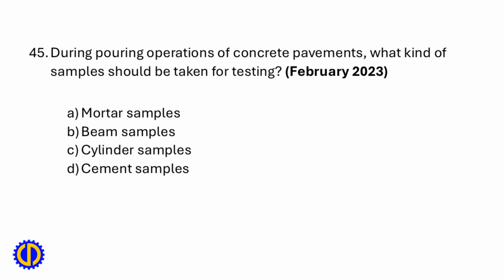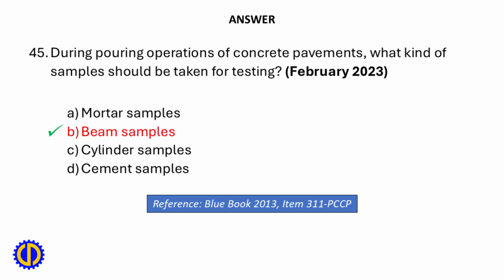45. During pouring operations of concrete pavements, what kind of samples should be taken for testing? A. Mortar samples, B. Beam samples, C. Cylinder samples, D. Cement samples. B. Beam samples. Reference, Blue Book 2013, Item 311, PCCP.